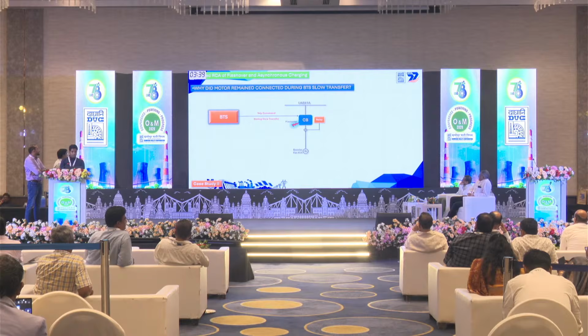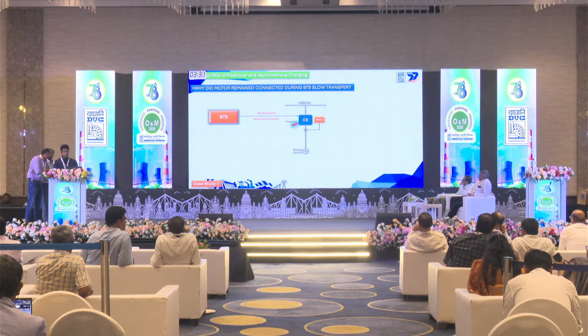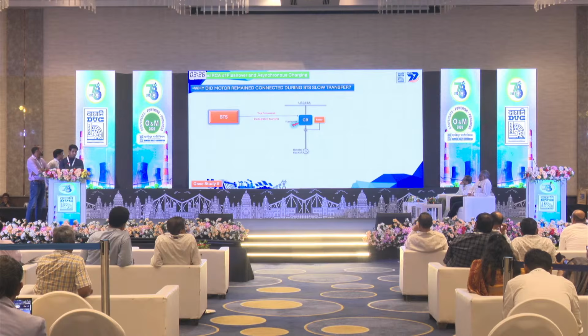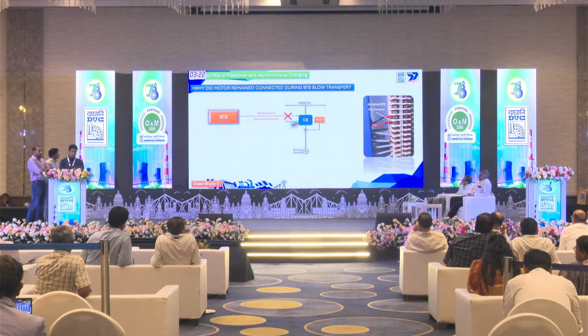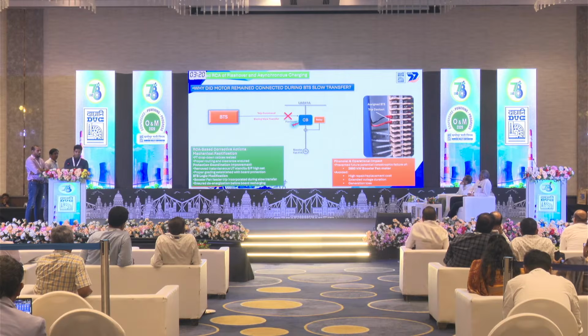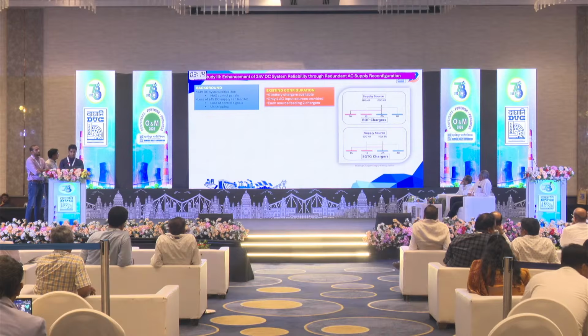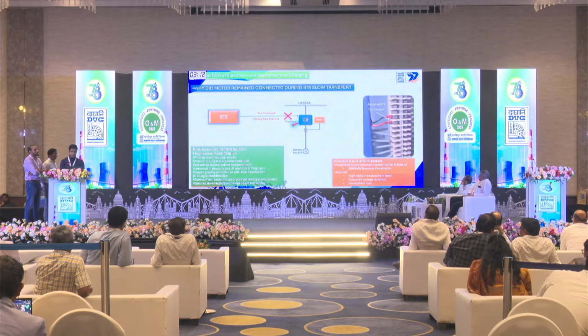The last concern was, how did the motor remain connected during BTS slow transfer? Actually, BTS always provides a trip command to the drives connected to the bus, especially the motor feeders. But in that case, it was a retrofitted scheme. In there, no trip command was there. So we made a modification in the BTS logic, and we assigned trip command for the remaining booster fans. And with that, we are confident enough that we will be able to prevent future catastrophic failure of this